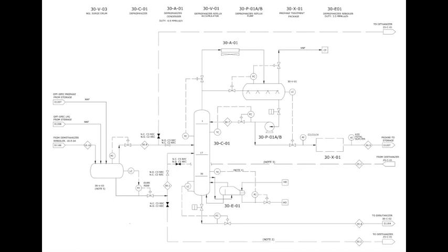Now let's consider this P&ID. As you can see in this P&ID, you will have the names of each equipment written. However, as we said, we put a letter, then three numbers. The first one will indicate the location or the area, and the other two numbers indicate the number of the equipment. However, here they have a lot of areas in the factory, so they put the area, then the letter, then the number of the equipment itself. Now let's read from left to right.